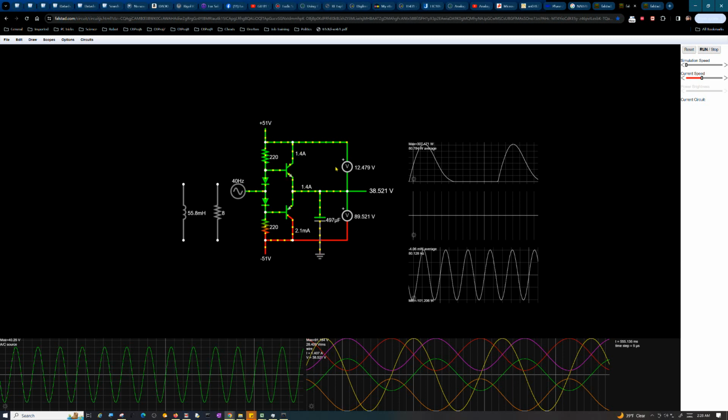So that means there's going to be extra power dissipation here that his ideal article wasn't really referring to, but it's still there. It's still a contributing factor, big time, in a practical amplifier. But at any rate, our peak current is 5 amps. Okay, what's the voltage across the transistor? Well, that's what I'm measuring with this meter here, and that's what that red trace is. Okay, so that's the current, but here's the voltage across it.